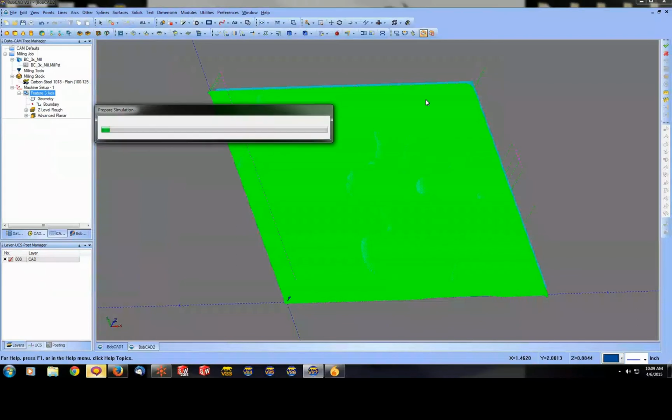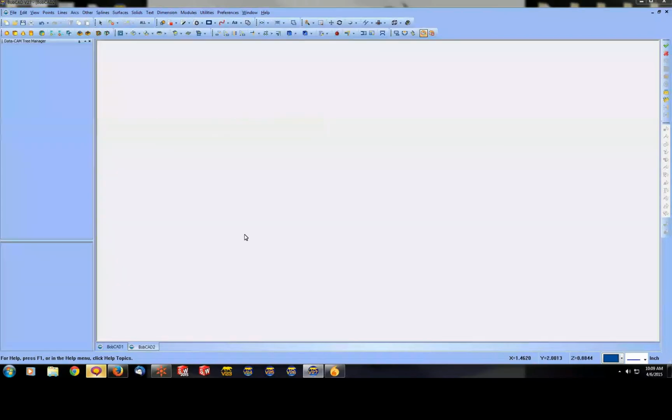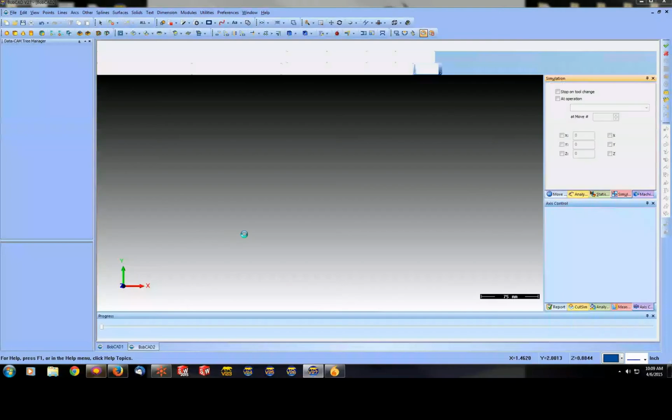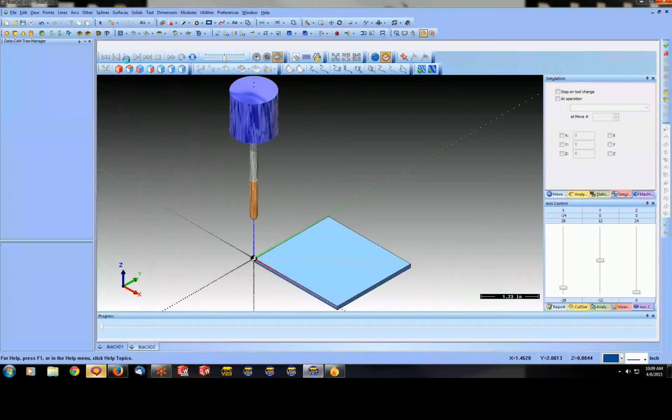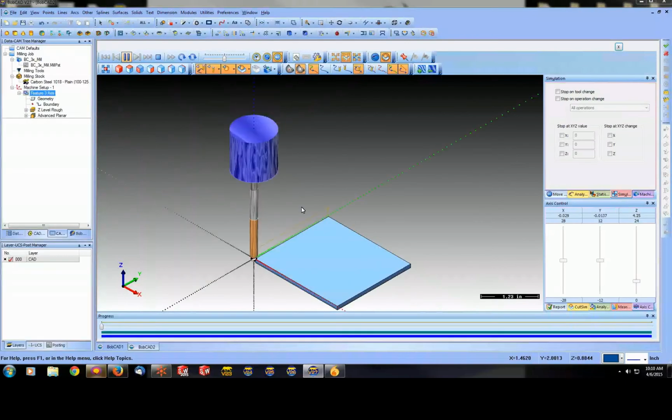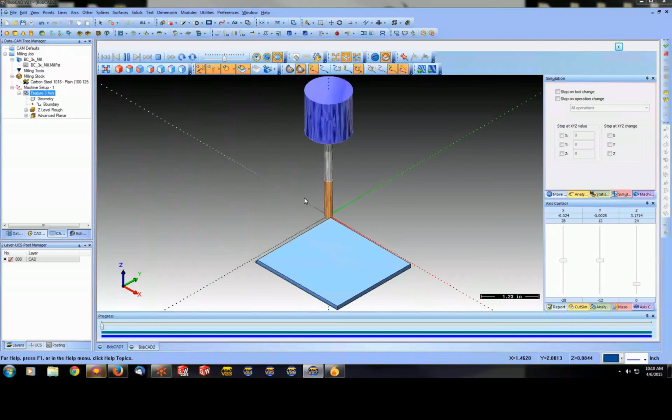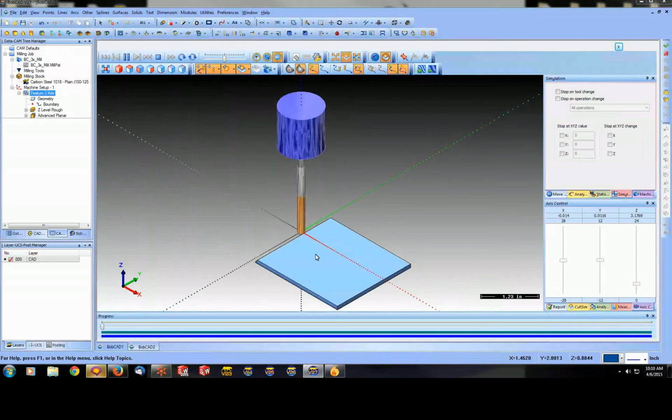Yeah, that'll get a lot cleaner. Essentially, whenever you have your STL mesh face, your actual embossment, any of the regular 3-axis tool paths, you can go through, and then the finishing with the planar and equidistant things like that, you can go through and clean up and mill it out.